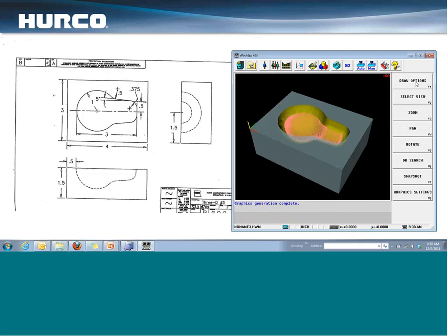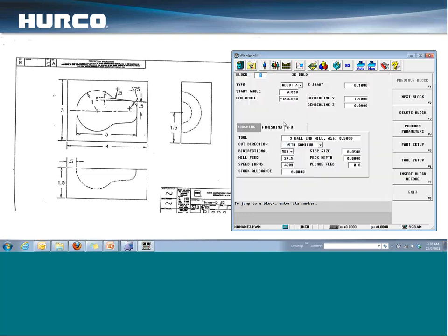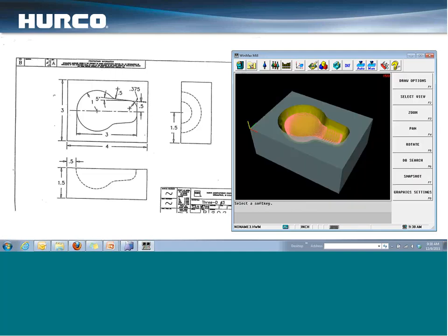And that is our 3D mold block. And you can see with the direction I had it set to, if we change that to be normal to it, you notice before it was cutting in this direction. If I switch that, it's now going to cut in this direction. And I have no peck depth in here, just so it's taking it all in one shot. If I did have the peck depth, it would step down by whatever your peck depth was, machine that out, and then step down to the next peck depth as well.